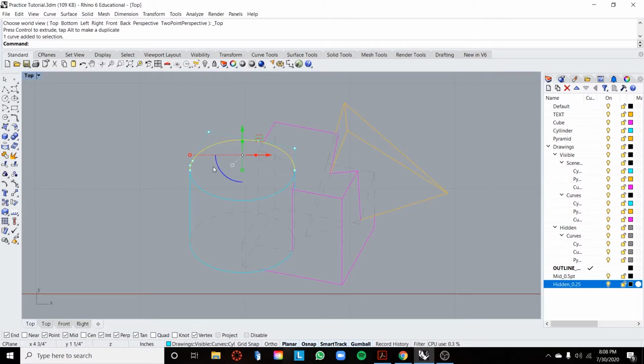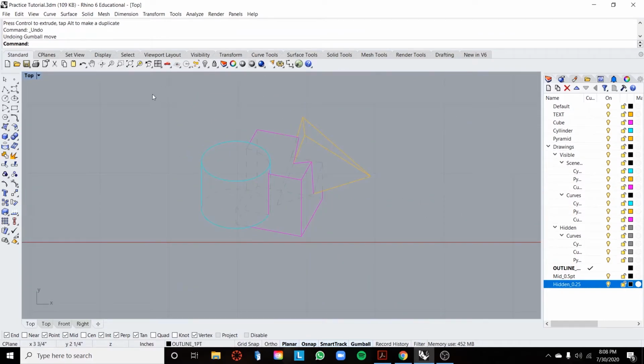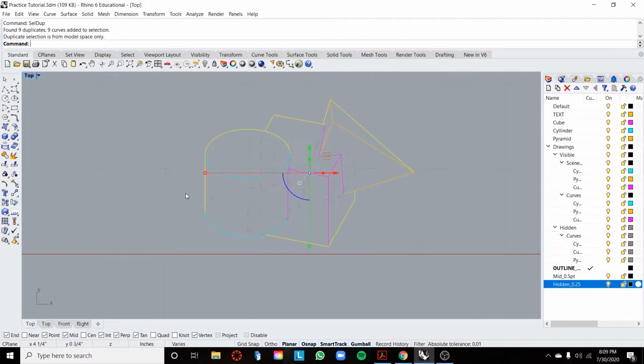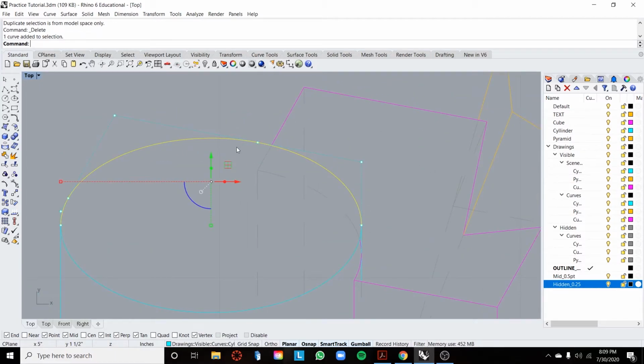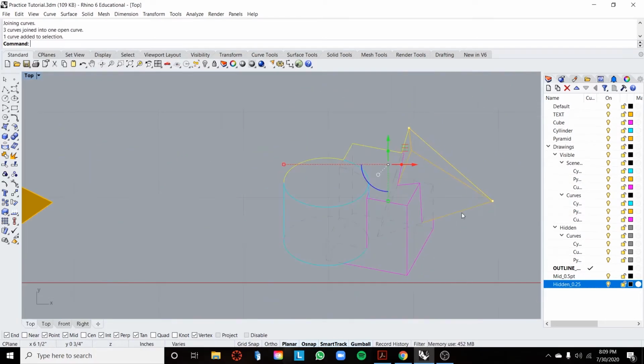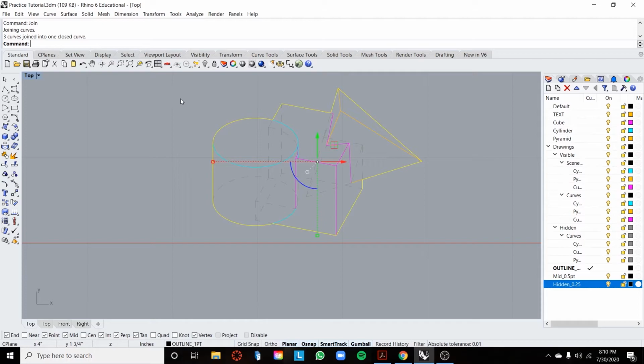All right. So one thing to note when you use scene silhouette is that this curve, you'll see it's duplicated. To get rid of any duplicated lines, you don't have to select anything, just type in SelDup. That will select all the duplicate lines, and then you can hit delete. So we're going to select this curve, type in split, and so now we've broken this curve up into 2 curves. And we're pretty much just going to be doing split and join to create our outline.